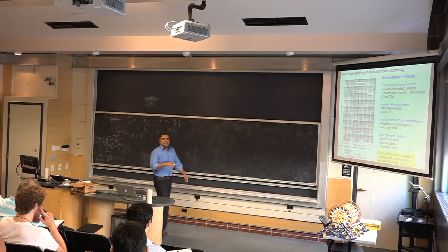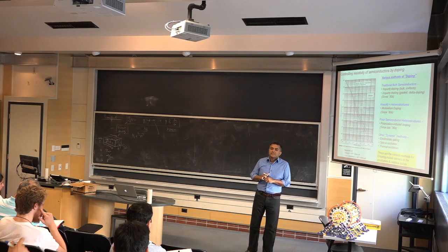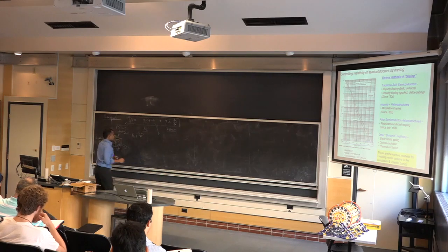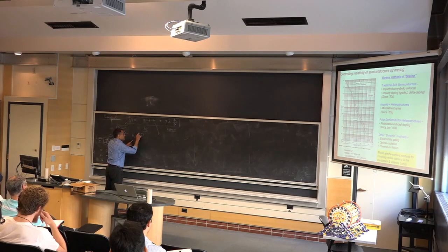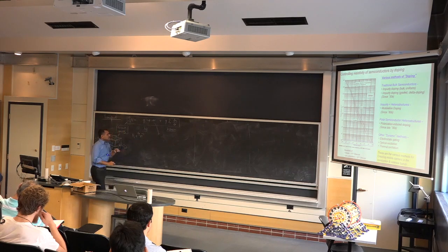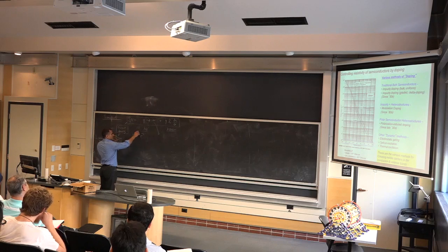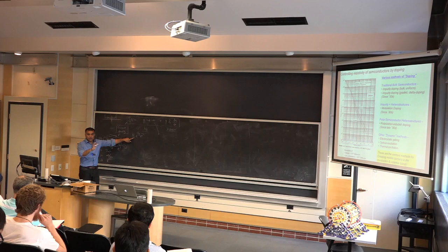Is this formula also valid in an equilibrium condition? Very good question. So the moment I apply an electric field, you're asking, is it in equilibrium? The answer is actually no. It's not valid in equilibrium. But what we will do is we are going to actually build into this formalism a change in our concept of the Fermi level so as to make this formula always valid.